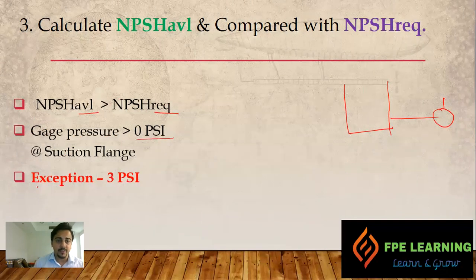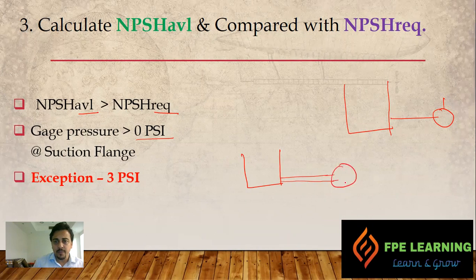With one exception, that exception allowed by NFPA, that if this is the suction supply tank and there is your pump at the same level, and when there is a fire for long hours and the pump is running for the duration of the hazard, like, right, let's say this is a light hazard, this is an extra hazard occupancies, and that need 150 minutes supply.